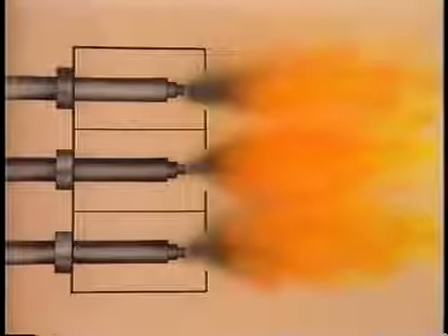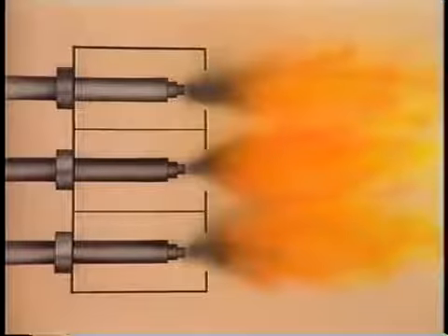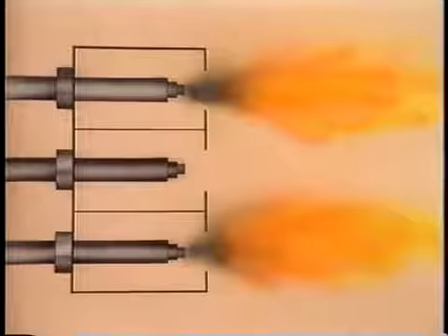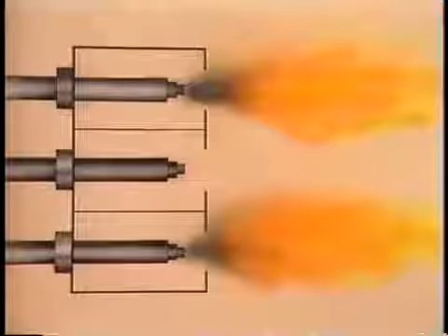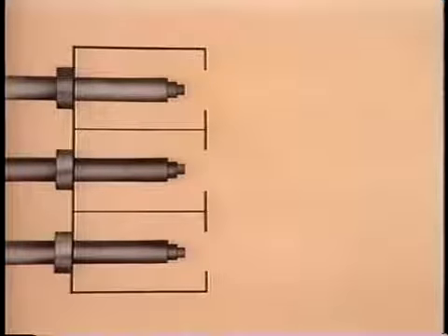If fuel flow to one burner is interrupted and the flame goes out, it may cause a loss of flame from other burners. In this example, if the middle burner flames out, it can't help support combustion on the top burner or the bottom burner. The result may be that the top burner and bottom burner also go out.